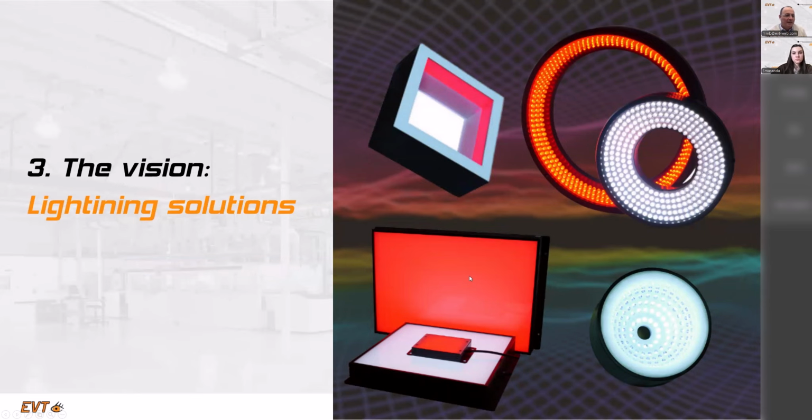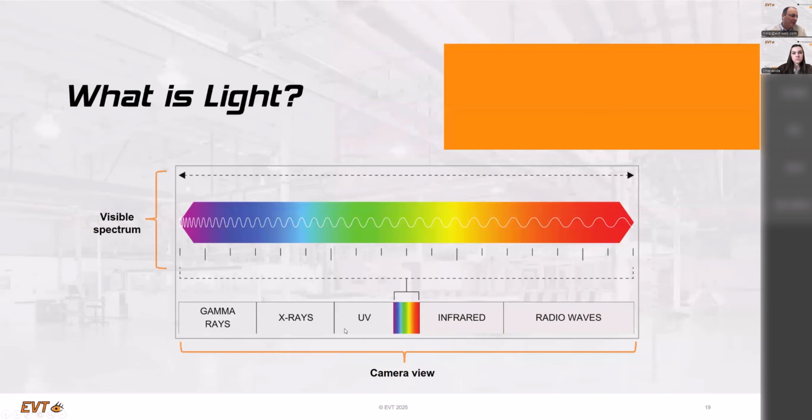As I said at the very beginning, light is really important. You have to think about whether you need a gray camera, a color camera, a 3D camera, a thermal camera, an infrared thermal camera, or a hyperspectral camera, and you see here these wavelengths. So you have to think, what is my application? Therefore, you first of all select also the light.